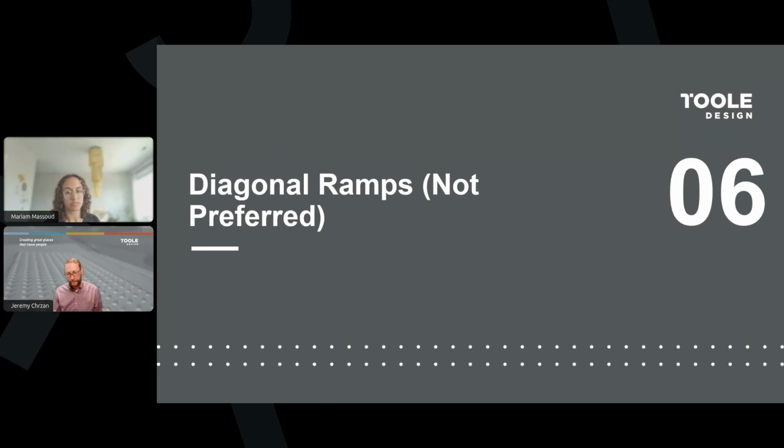So that's a comparable rule of thumb that I would use for crossing pedestrians: if you're 25 feet away from the intersecting roadway, that's just going to be too far away to make that pedestrian easily visible to a crossing user. Similarly, you don't want to put it right up against the edge of that travel lane because it gives no space for a motorist to yield to a crossing pedestrian.